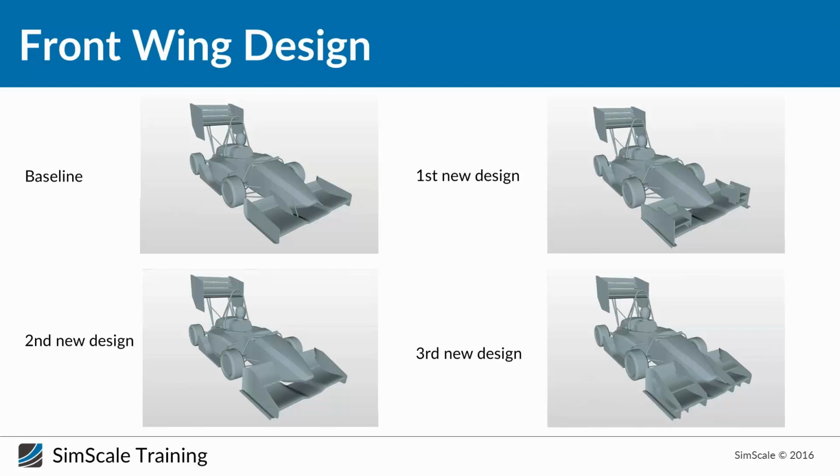So, guys, we have based our simulation on the same setup that we used in the previous homework. We have just changed the front wing of the different cars. And as you can see, our baseline was mainly designed, I believe, for a medium downforce configuration. So we have tried to increase the downforce, and of course increasing downforce is achieved by increasing the elements on your wing, or also adding some extra elements on top, like cascade elements.